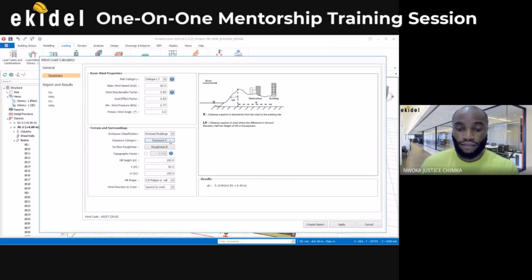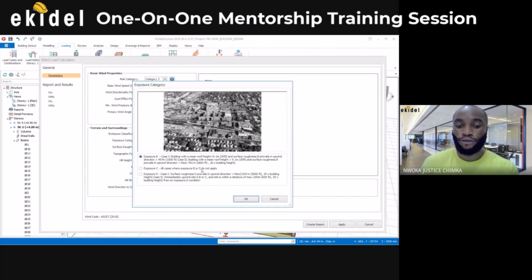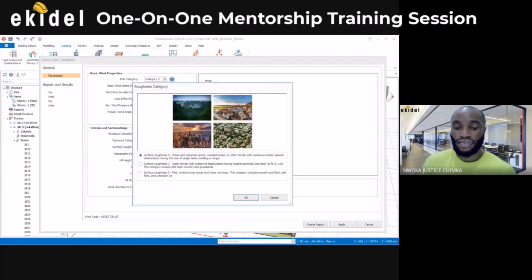Okay, so in this case, let me assume that it is built in a city. So I'll choose category B and say okay. You can see that we have less wind pressure now, which is normal. Then also, surface roughness is almost the same as what I just explained on this category. But if I click here on roughness, you can see surface roughness B is saying urban and suburban area, right?